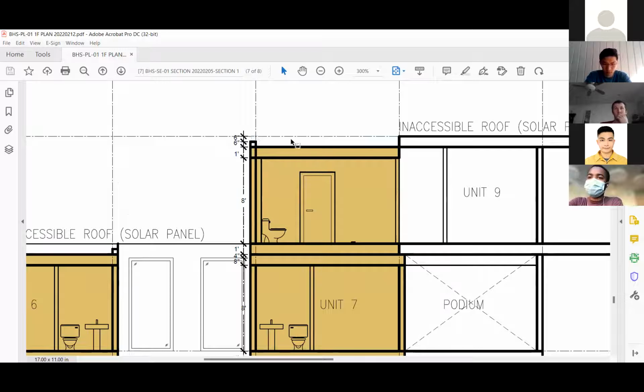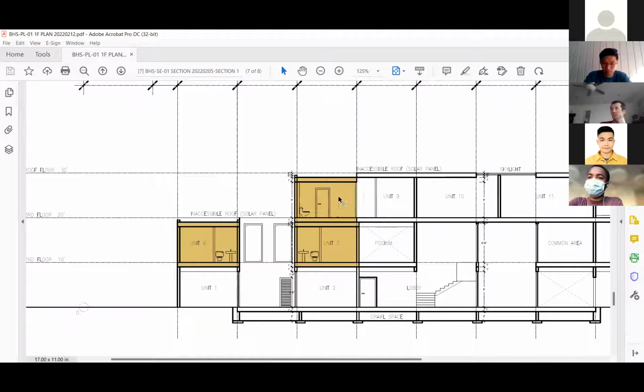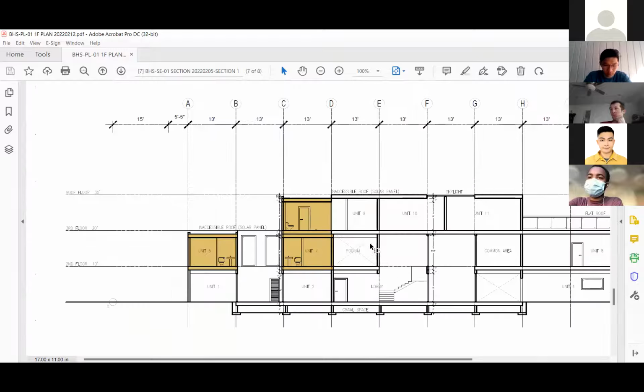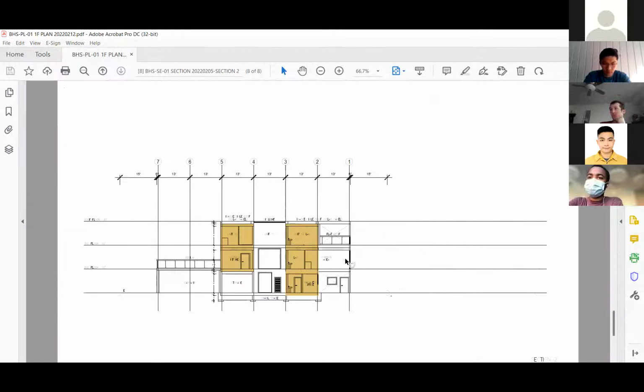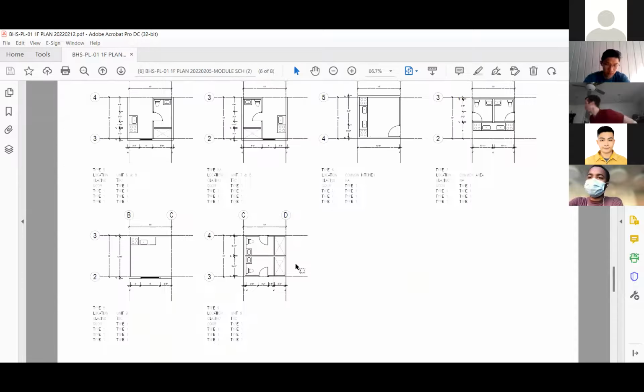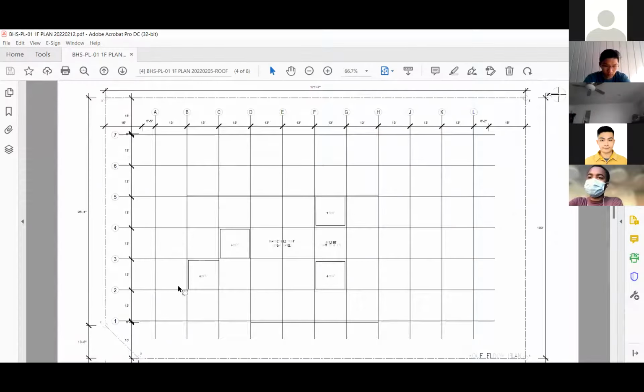So she recommended we just leave the ceiling panel of the module as a part of the roof, and it would be replaced by a parapet to wrap around the perimeter of the roof, leaving it around 1 foot deeper. But at the same time this could also be beneficial, to demarcate or prioritize where the drainage areas would be.